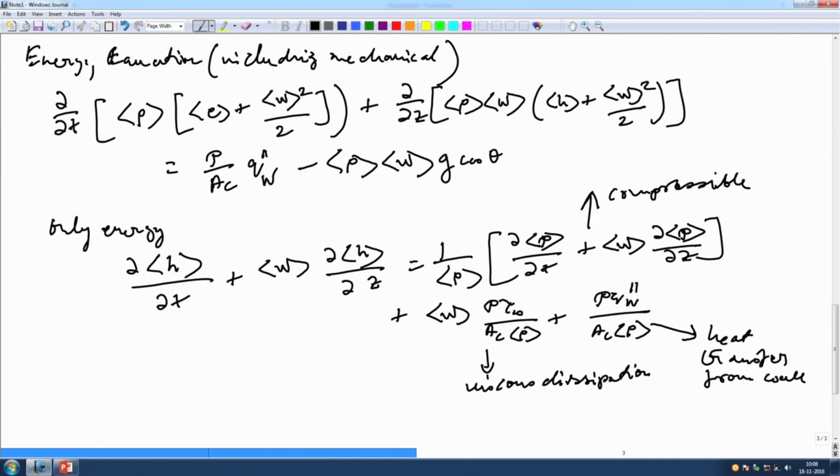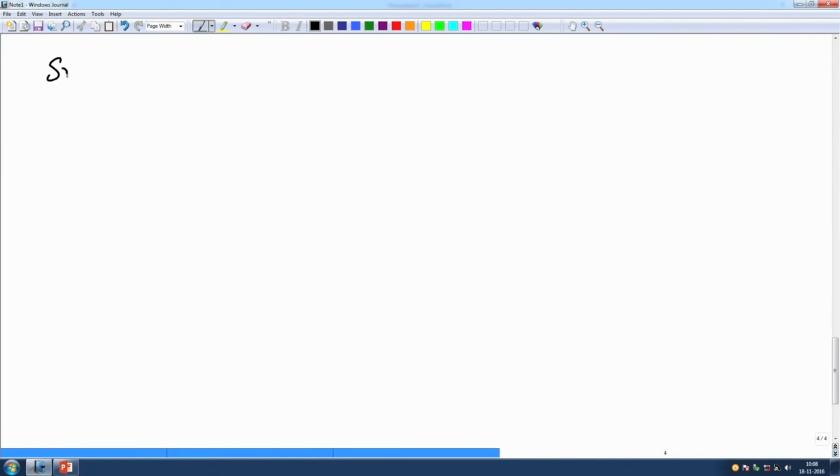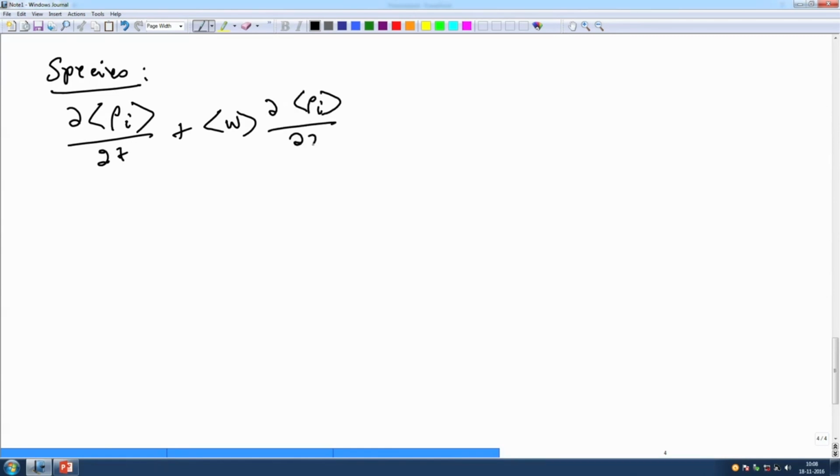As you can see, it is much simpler than the volume averaged equations that we wrote. There is only one more equation left after this, which is the species balance. The species equation is almost exactly like the energy equation, sorry. This is Ji plus the corresponding Mi. So, this is basically the source and sink term.